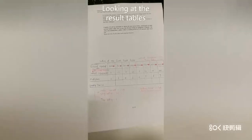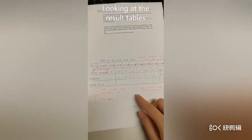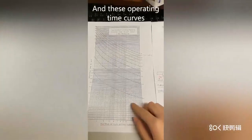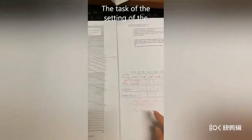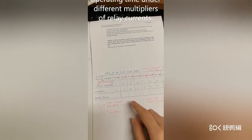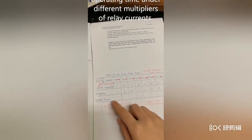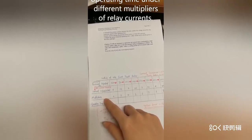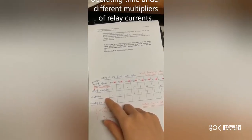Looking at the results tables and these operating time curves, the task of the setting of the Earth fault relay is to measure a number of operating times at different multipliers of relay current.